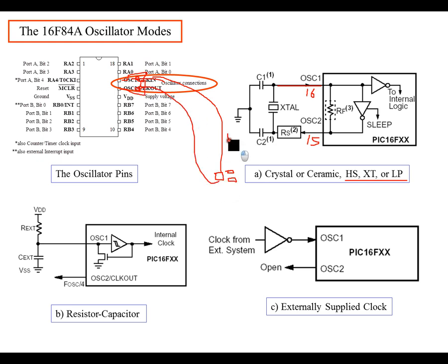This is going to have a bunch of inductance in series. Mainly, it's going to be due to inductance. That inductance is going to mess with the resonant frequency of the crystal, and it's going to shift that frequency. Okay, so you don't want to have these long wires. These long wires have magnetic fields around them that cause an inductor, and then this is an L.